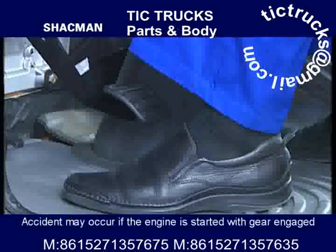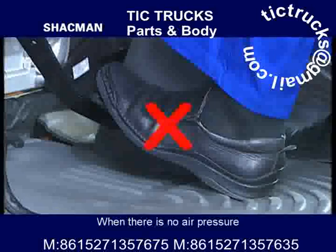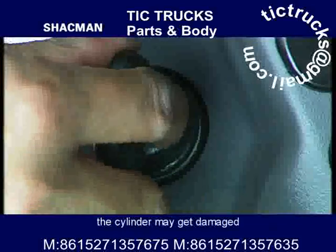Note: accident may occur if the engine is started with gear engaged. Don't push down the clutch. When there is no air pressure, the clutch pedal can't be pushed down. If it is pushed down forcefully, the cylinder may get damaged.